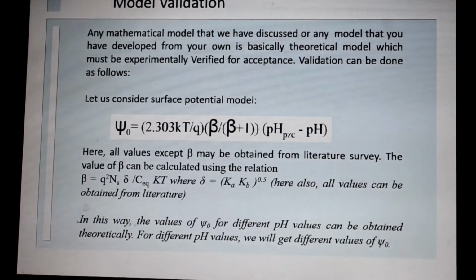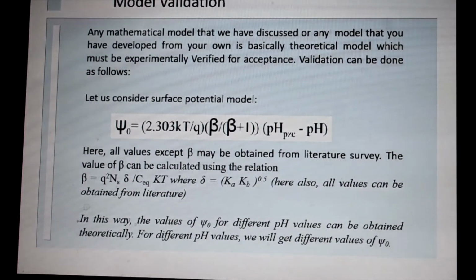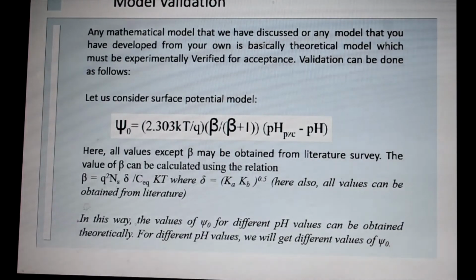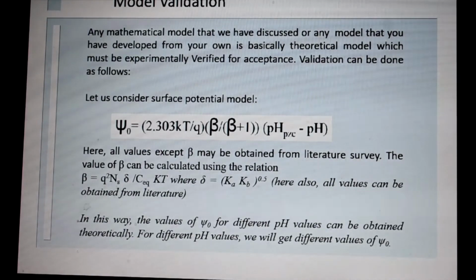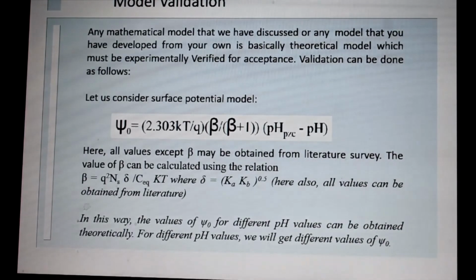So also you know that threshold voltage of ISFET is pH dependent. That means that at different pH values, you will get different xi naught values. So first, from experiment, you find the threshold voltage of the ISFET device experimentally by plotting the gate to source voltage versus IDS curve. For different pH values, you will get different interface potential xi naught. From this you make a table.